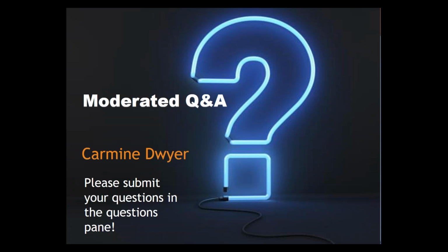Okay, great. Thanks, Anna. Next question, has there been any consideration on the design of the pavement markings so they won't be so slick for cyclists if it's wet outside? So, a friction question. We had talked about the preformed thermoplastic a few questions ago. Our spec book actually requires a certain friction level for that type of material.